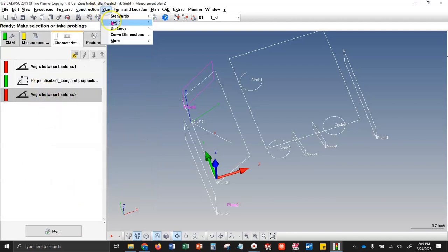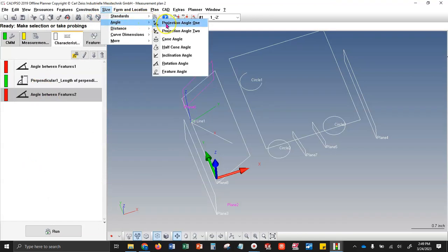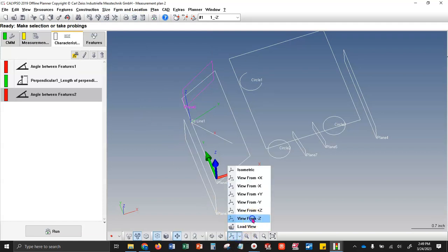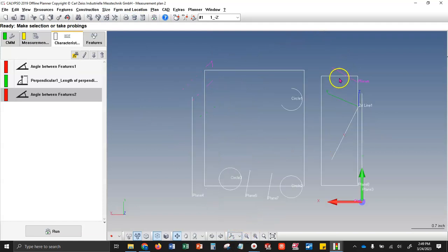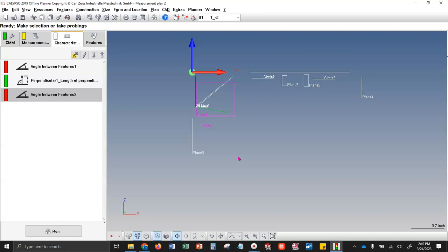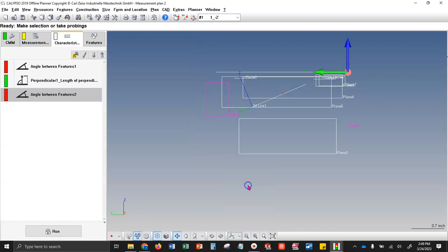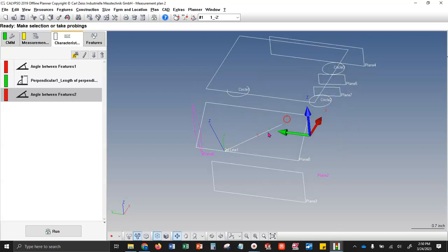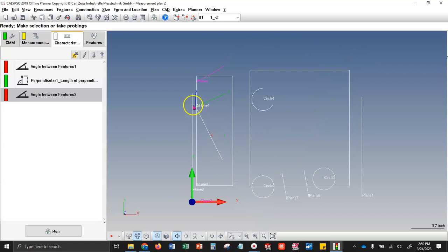The issue with the others, the size, angle, and picking from one of these four options here, the reason that those exist is if you're looking at the angle from the top, you're seeing a different angle than if you're looking from the front versus if you're looking from the left side, right? So in each case, let's say we take 2D line 1 right here, which I just drew as a sample. If we look at the angle of that line from the top view, that looks like, I don't know, somewhere around a 45 degree line going negative.